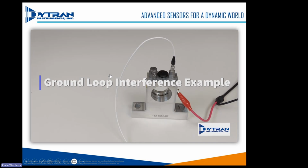So here's a good example. This video, the first accelerometer here is on this energized test article, and it has an accelerometer that's not isolated. And then we're going to move it to the isolated base, and then we're going to move it to the isolated accelerometer. We're going to hit the table with a hammer and see what happens.